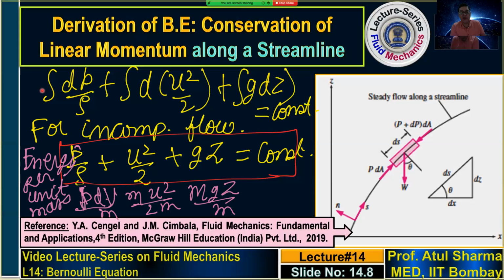This is the first form of Bernoulli's equation. I will show you two additional forms of the Bernoulli's equation. When I say a form, I mean what is the unit, or what is the physical quantity that each term of the Bernoulli's equation represents. In this case, each term represents an energy per unit mass. So you can call this form of the Bernoulli's equation the energy form. In a later slide, I will show you two more forms of the Bernoulli's equation, called the pressure form and the head form.